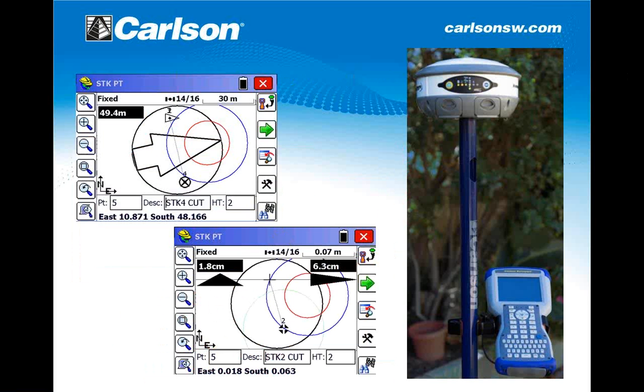Right, so it is important whenever you work with a receiver that only has tilt sensors like this one, you need to face the panel of the receiver, as you can see in the picture, just to make the bubble motion match with the direction of the unit. This is something important to consider.